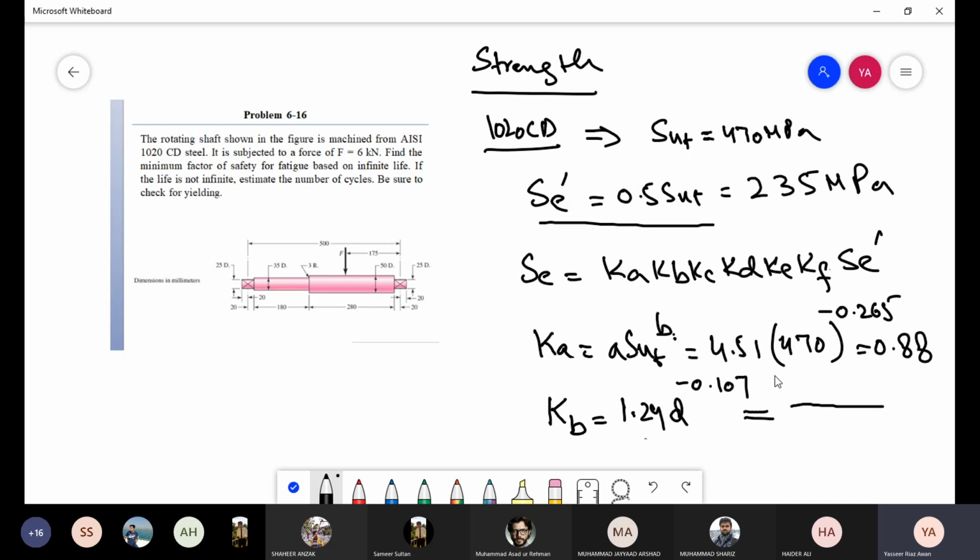Okay, so our enterprise is doomed before calculating the stresses because first we have to identify which is the critical point in this shaft about which we want to calculate the stress and solve this problem. Without that, because we don't have a computer, we would have to calculate the stresses at all points and the strength also at all points and compare at all points, but we can't do that. So first we have to identify the critical points on this shaft at which we would calculate the stresses.